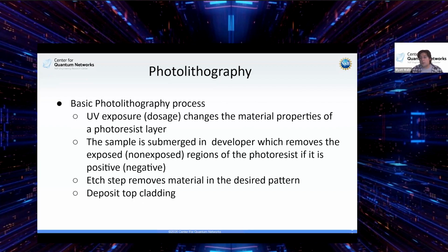Which photoresist you use will decide how much dosage you should have. Dosage, measured in millijoules per centimeter squared, is essentially an idea of power: how intense of a beam are you going to illuminate the photoresist with? Because if you don't illuminate it enough, you won't have that chemistry happen inside of the photoresist. It won't develop right. And then when you go to your etch, the whole architecture is wrong. So yeah.